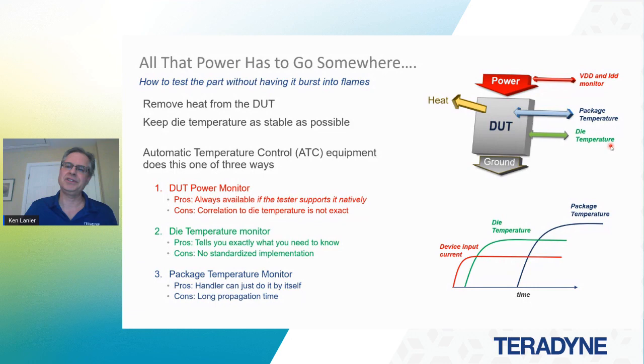And so there is a pretty significant lag if we have to do a bunch of digital readbacks from the device, make a decision, and send information to the handler. There's a lot more lag time to it than if we just send over a couple of analog signals in real time. The last thing you can do is monitor the package temperature.